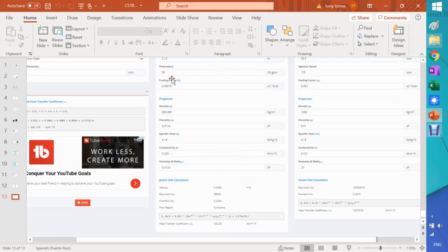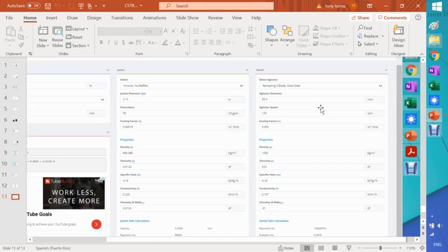Now for the tank, or inside the vessel, that's highly dependent on the RPMs, the size of the agitator and the type of agitator, so you can pick those. Now here you see a fouling factor that is very high, 0.0002. I will say that this value should be